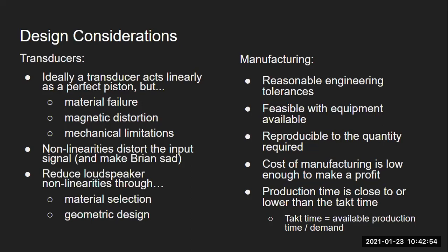So in order to reduce those things, what a transducer engineer is doing a lot of the time is choosing their materials carefully and the geometry of it. The third thing there is that you're choosing materials and geometry for a certain design. That's a more modern approach to transducer design: not trying to make a general transducer that works well for many things, but, in the last 15 years, we've seen companies designing transducers specifically for applications, for certain sizes of enclosures, for certain dispersions that are required.